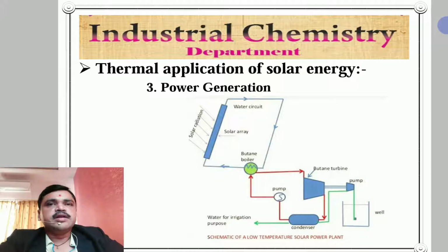From the storage tank, it flows through a vapor generator, through which the working fluid of the Rankine cycle is also passed. The working fluid has a low boiling point, and vapor at above 90 degrees Celsius and a pressure of a few atmospheres leaves the vapor generator.